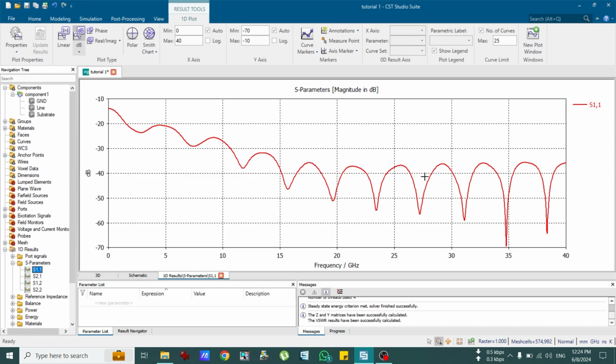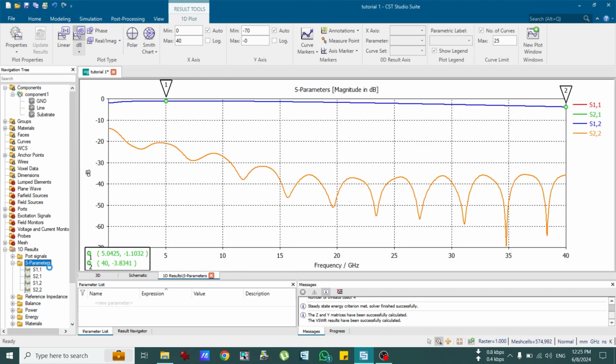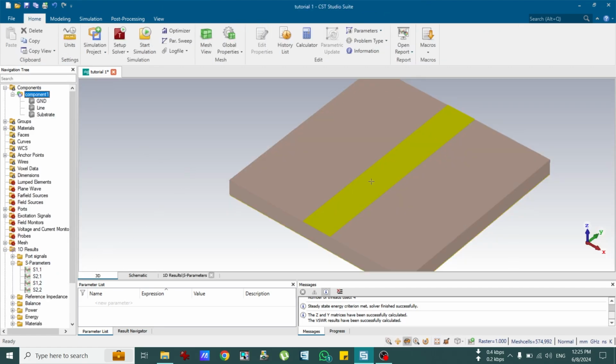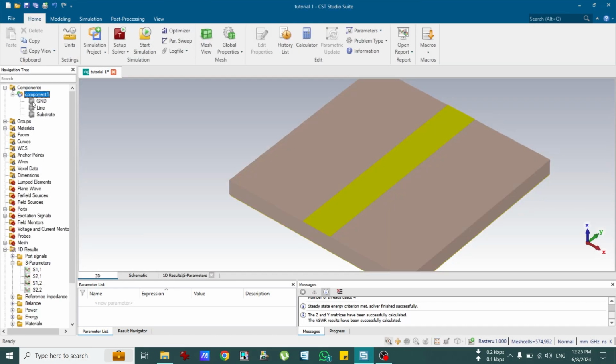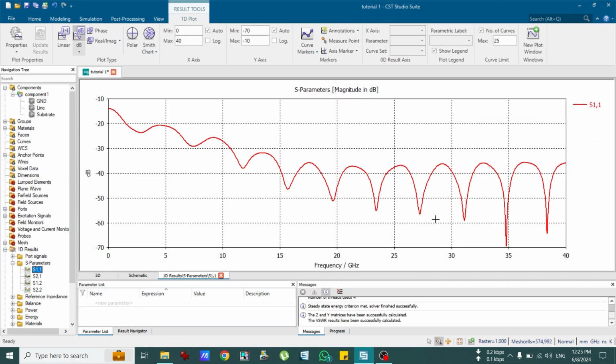The reason for these multiple dips is that for higher frequencies, such a transmission line starts to radiate. Although it will not have good efficiency and gain, it will still radiate. That is why we are looking at these dips, right? So these dips are showing a kind of radiation, since the standing waves are quite minimal right here.